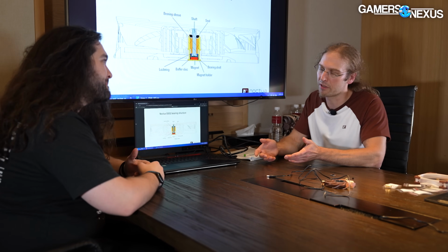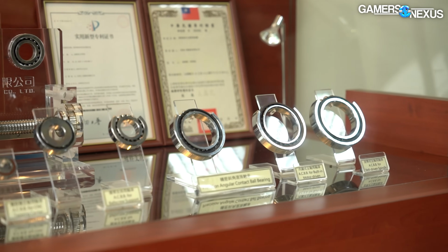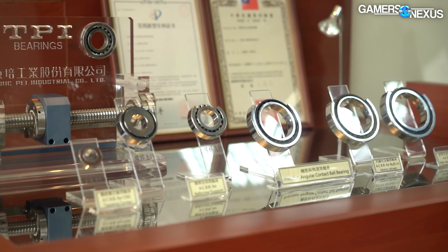The load bearing capacity, of course, is another key factor. A rule of thumb that you could throw out is that ball bearings are better at higher temperatures. So if you want to go beyond a 70-degree operating temperature, a regular sleeve bearing is not going to cut it.